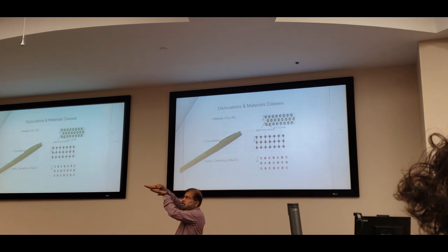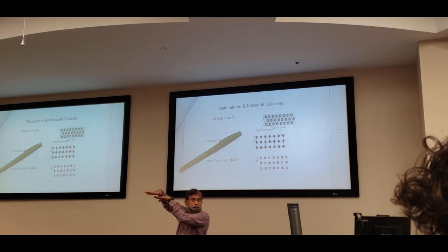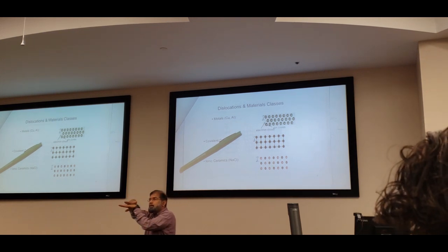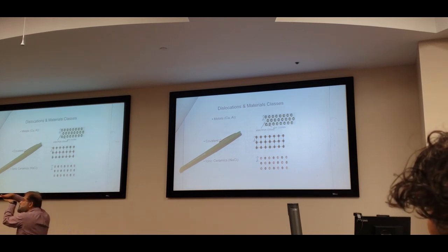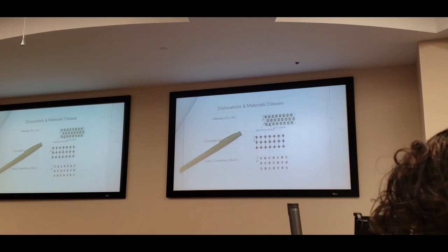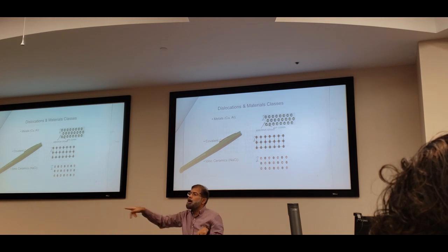So it is easy for this plane of atoms to slip, right? Move from one point to another point. Do you agree? It's like a lubricant. You can move this one. Once you have a plane of atoms move on top of the other, what is that process called? That is the dislocation. You can consider it as a dislocation, as it is the movement of the planes. So the dislocations can move from one point to another like this, and that is a plastic deformation.